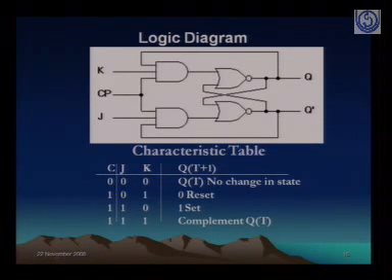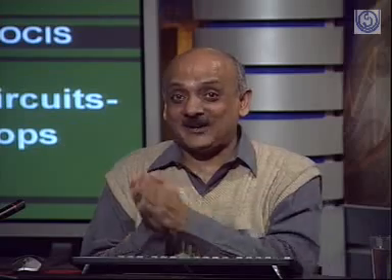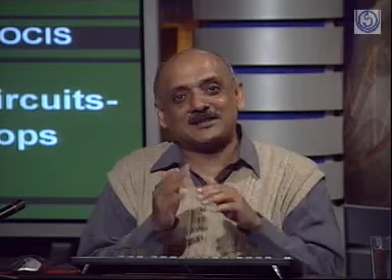Once again I would like to say, a little bit of modification, a little bit of use of your logical analysis, and you are able to bring in very, very interesting situations as far as flip-flops are concerned. Flip-flops are very important devices for the construction of sequential circuits. Why? Because they are able to store information. Using only AND, NOR, NAND gates, these are all combinational circuits, but the combinational logic and feedback result in storage of information, and that actually resulted in the development of these discrete devices. You see where we are now.